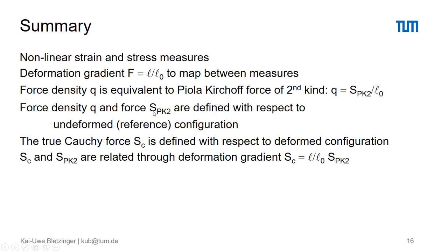The force density and the Piola-Kirchhoff force of second kind are defined with respect to the undeformed reference configuration. We see it here. Both of them are defined with respect to the undeformed configuration, which means directly that the Q, the force density, is also defined, first of all, with respect to the undeformed configuration, and important to realize, it remains constant throughout the complete deformation history.